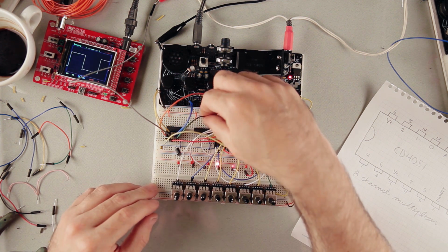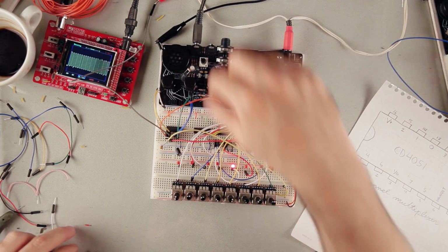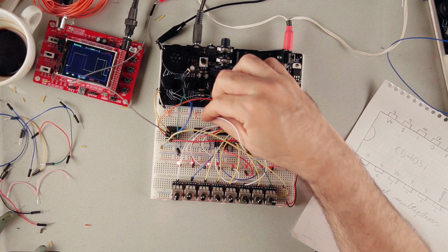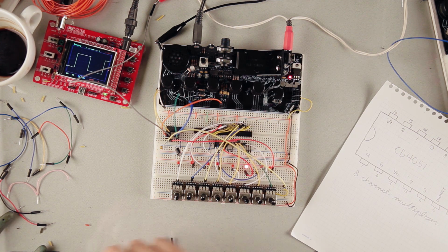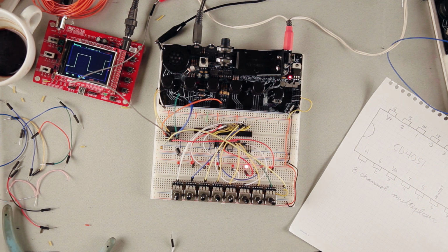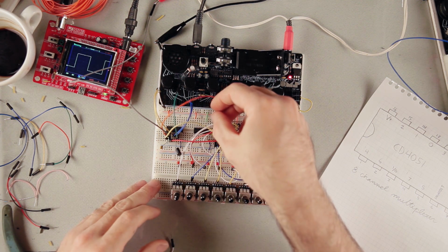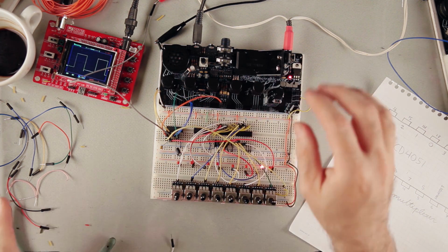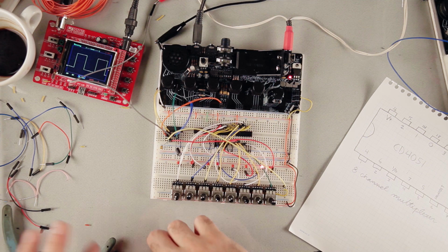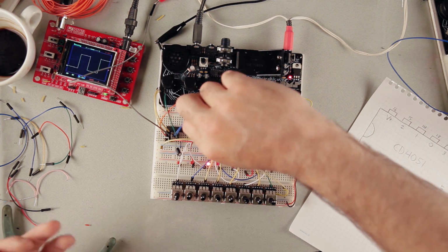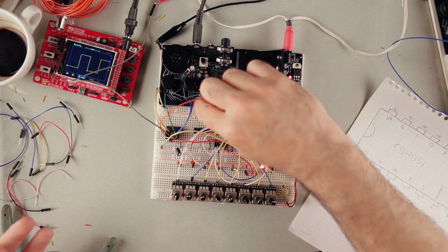And then if we want to just program one note at a time, what we can do is go to the clock input of our 4040, and first what we're going to do is pull it low. So this is the clock input, putting a resistor to ground. And that's just so when nothing's plugged in, it won't get noise, because you could see when I did that, that's noise, which can be cool, but that's not what we want.